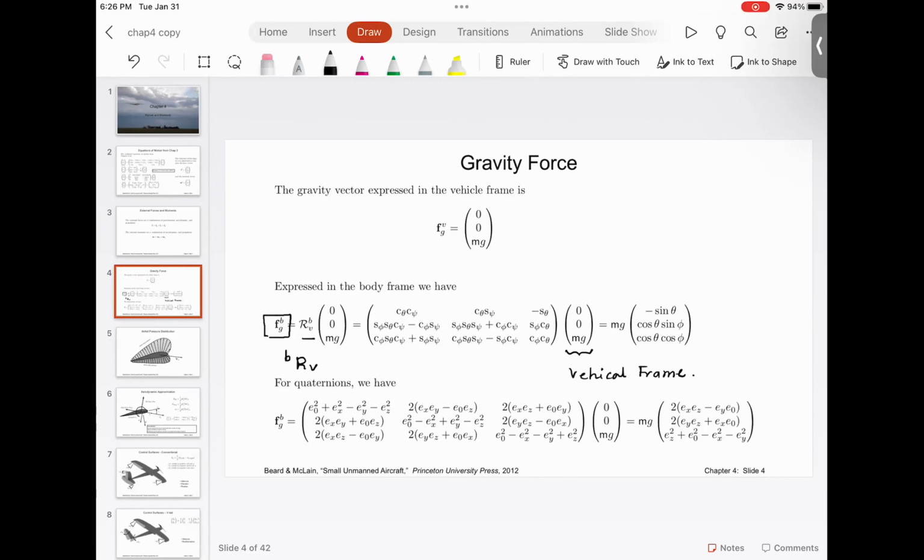So for an example, I give you a very common example. Say you have an aircraft that takes off. Typically, the aircraft will not have a large pitch moment, so it will be at a certain pitch angle. And you can find out f of x, f of y, f of z measured by the accelerometer, and then find out the values of theta and phi. So you can find out the value of theta and the value of phi based on accelerometer measurement.